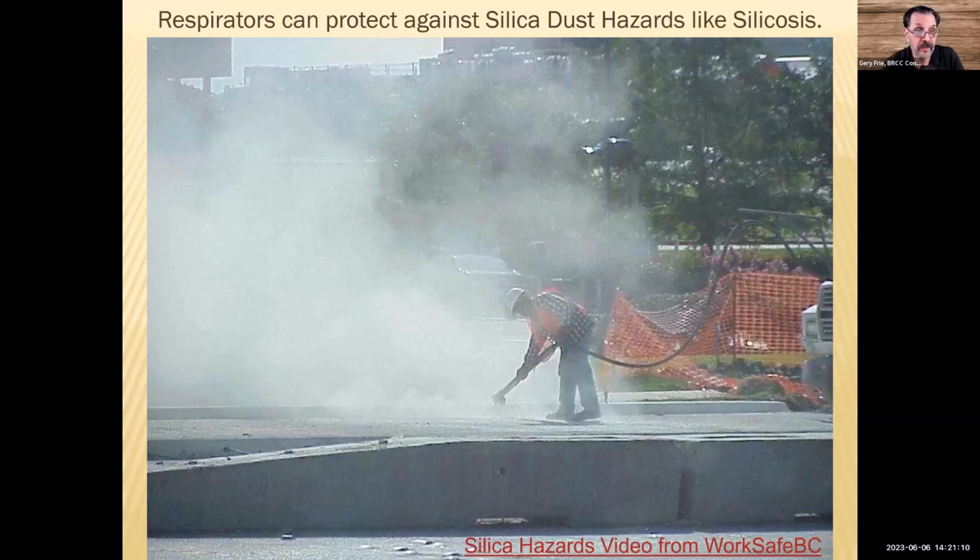Okay. This guy's blowing all kinds of silica dust all over the place. And so he should be wearing a respirator. He might be, I can't tell in this picture, but anybody around you needs to be wearing a respirator. So you're no longer allowed to do this. It used to be allowed in some cases until about 2015. OSHA really clamped down on the silica exposure in construction.